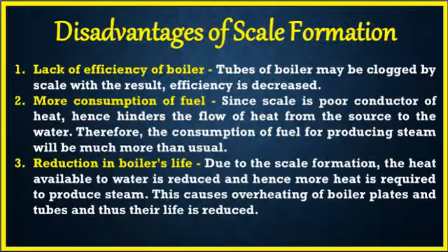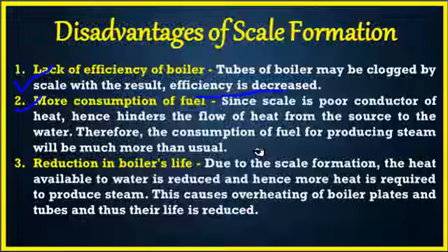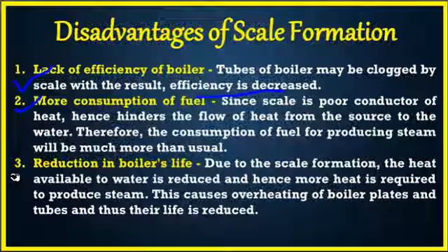Now, disadvantages of scale formation. First, efficiency of boiler decreases. The tubes of the boiler may be clogged by the scale, with the result that the efficiency of the boiler decreases. Second, fuel consumption is more. Since scale is a poor conductor of heat, it hinders the flow of heat from the source to the water. Therefore, the consumption of fuel for producing steam will be much more than usual.